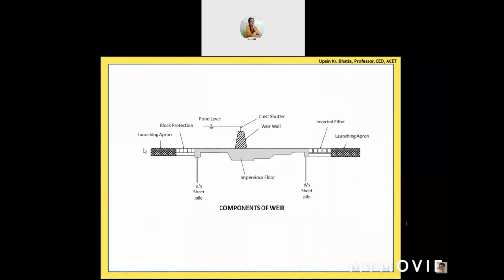Okay, so for that seeping water, here the pressure is very high, and at the downstream end the pressure is zero, and in between everywhere the pressure will be reducing from a high value to a zero value. So in between it will be a non-zero value. In between, the water will be at a pressure which is non-zero, less than the initial pressure, but definitely more than zero.